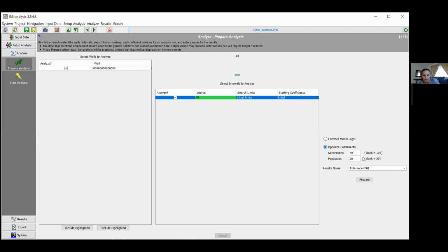I'm gonna change it. You can change it to 40 and 5. You can change any of the two. It's still pretty fast because remember what it's doing now is gonna test 40 generations multiplied by 5, so it's gonna test 200 constants. The thing that we did before, it's gonna do 200 times this way. If you had the default, it's gonna be 2,000 times. It's not too long anyways.